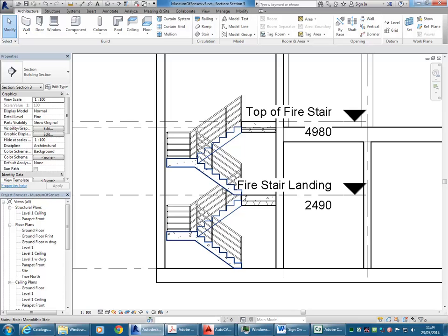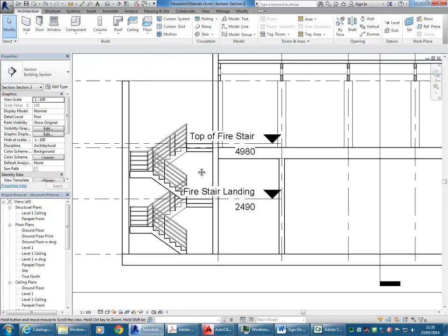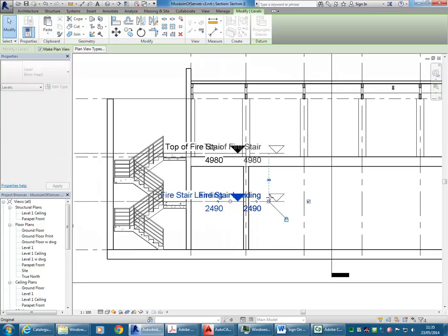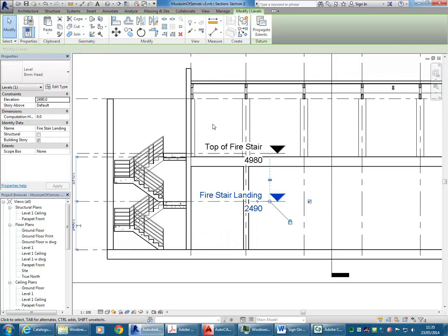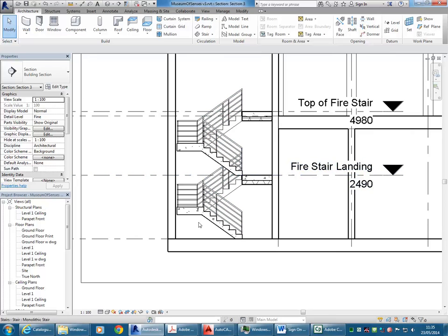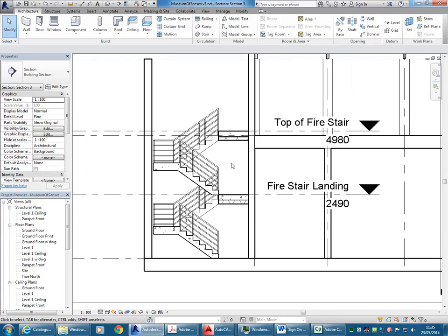Where the stair isn't, the landing goes all the way across to the stair and comes up to halfway, and then there's the other half where it would be a little bit fuller. But the stairs only come up to half of that. This is all existing. So if you're changing this stair, then you could detail it and draw it up properly. Otherwise, it's just indicative to show there's a fire stair there and that you've got an idea what's happening with the landings and the railings.